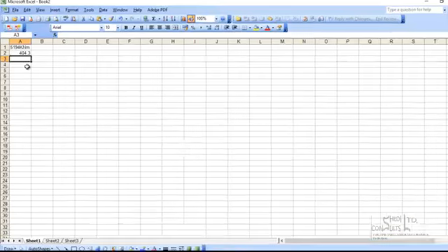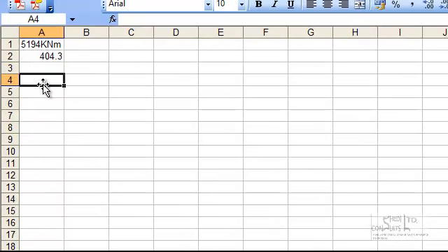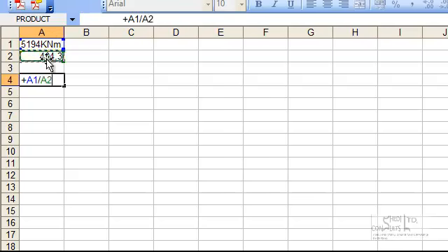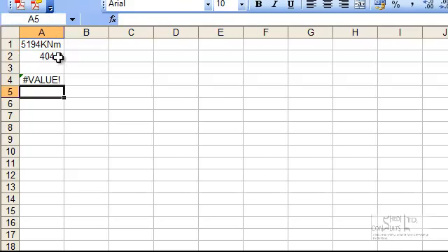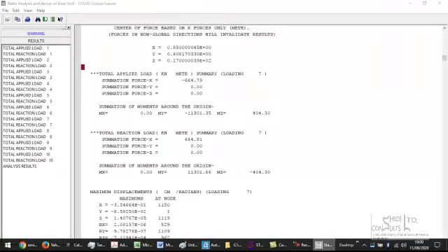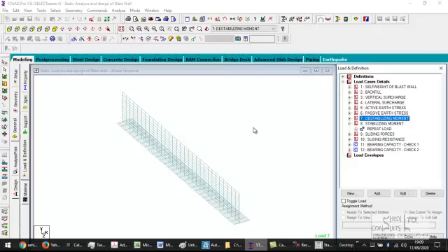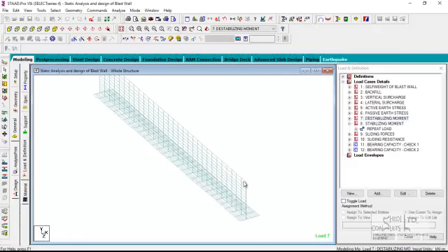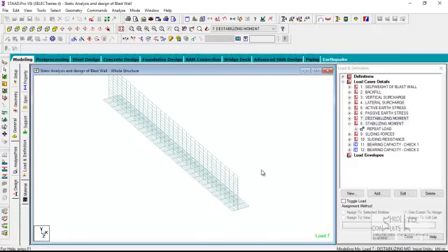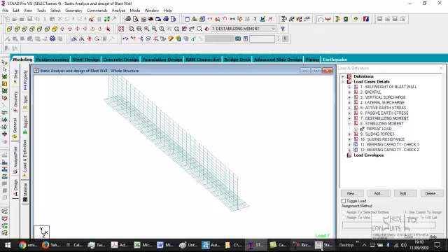So you can get the factor of safety against overturning by getting the ratio between these two values. You can see it's far more than 10. The factor of safety against overturning is about 12, so it's very, very satisfactory. The structure is very satisfactory against overturning. One of the contributory factors is the weight of the structure, which is quite significant and prevents the overturning forces from being significant. So you can check the factors, and you can check the stability against sliding.